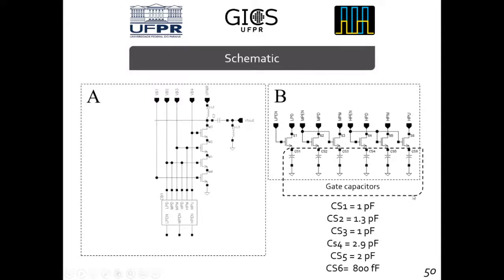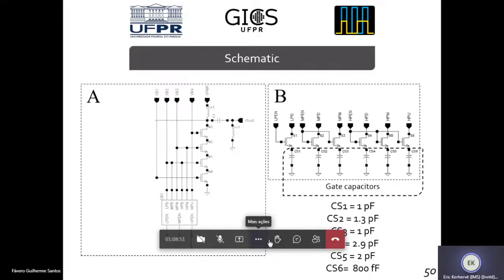Yes. These gate capacitors were all optimized. What I had to do was to optimize each one of them regarding the mode of operation of the transistor. Actually, sorry, after the design, it's not possible to change the value of each gate capacitance. What I'm presenting here are not the schematic values, but the updated values that I obtained after post layout extraction. After the fabrication of the circuit, it's not possible to change the value of the capacitance, right? No, this is a fixed setup of capacitance.